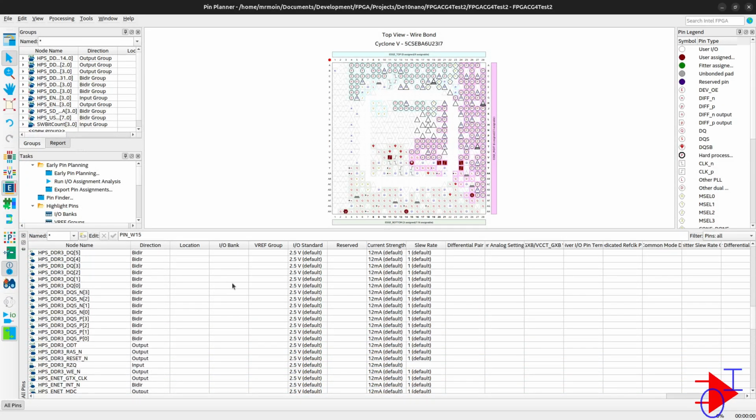these others. What happens is when we execute our project, TCL scripts and the entire project, we have to execute it twice. FYI, maybe the first time the TCL scripts won't connect all the way, so maybe we have to do it again. But essentially what happens when we execute the compilation goes through these pins, automatically checks the name.